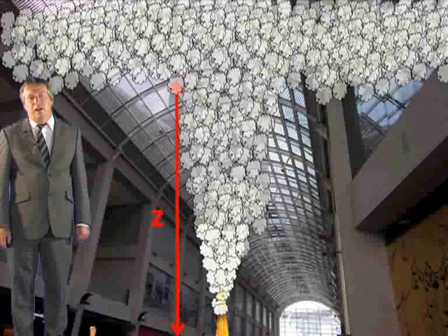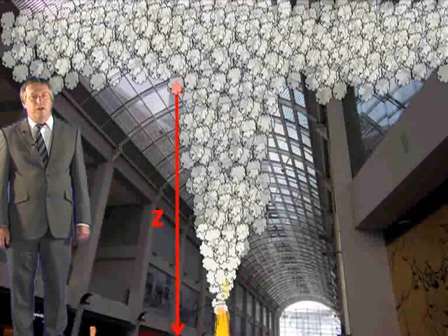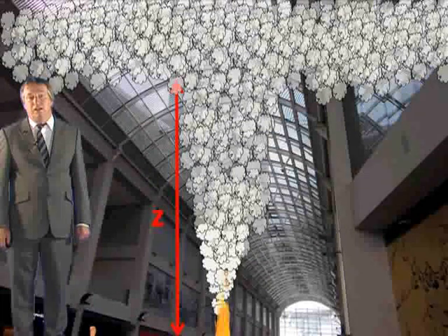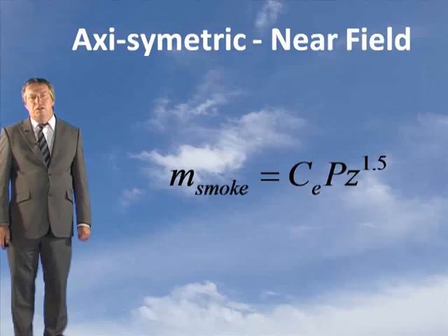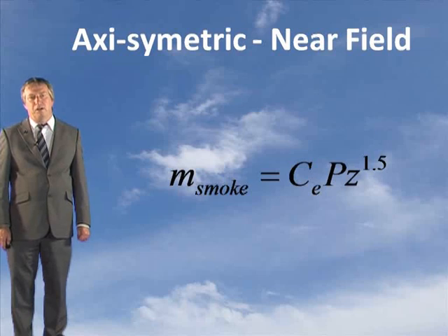As well as being the clear layer height, it is of course also the height through which the smoke plume must rise before it enters the smoke layer, assuming that is that the fire is in the worst possible location, i.e. on the floor.